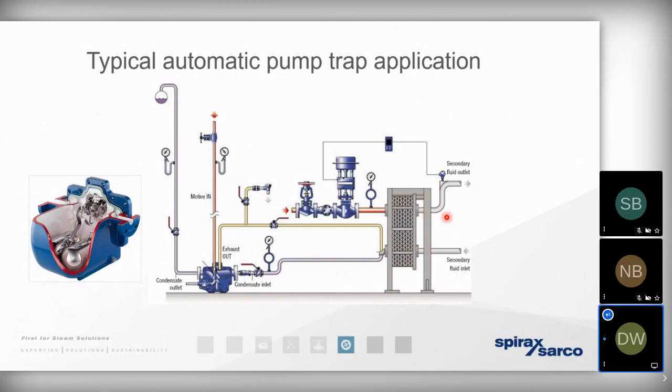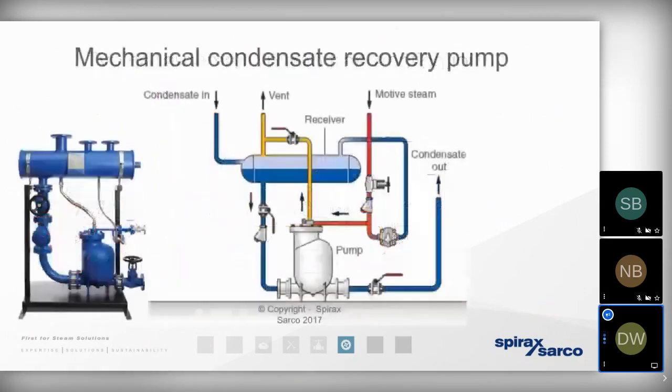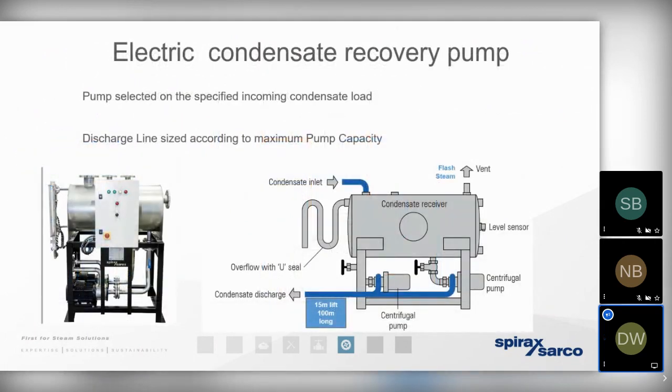Now, our first instinct may be to point the finger of blame at the heat exchanger, at the control valve, maybe even at the steam condition, when in actual fact, it may be simply down to the fact that we're not removing the condensate at the appropriate rate. So when we talk about steam condition, condensate is critically important. We need to ensure that we're moving the condensate away from the process in the appropriately sized and selected condensate pump, for the simple reason that, as we've mentioned previously, condensate is not only hot water, but it's also hot water that has been chemically conditioned.